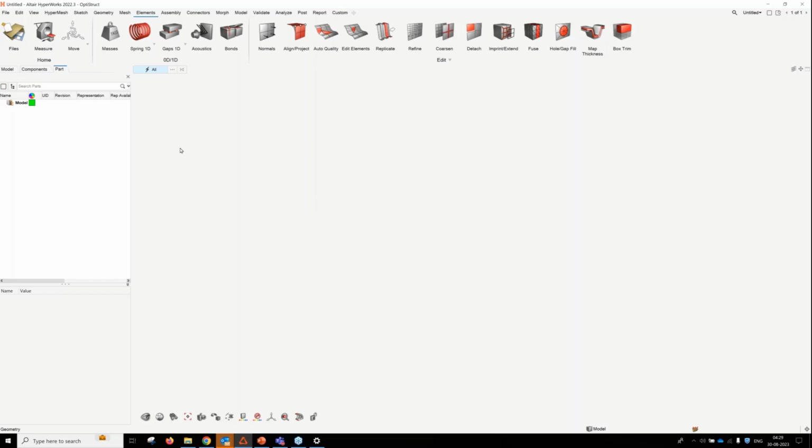Lastly, if I want to talk about the measure tool, it works with the background of snaps. You just hover your mouse on a hole region or any line, and it will tell you the length or radius of the line. If you want to draw a line, it will also tell you whether you're drawing perpendicular or going away from perpendicularity. The measure tool does that for you with the help of snaps.